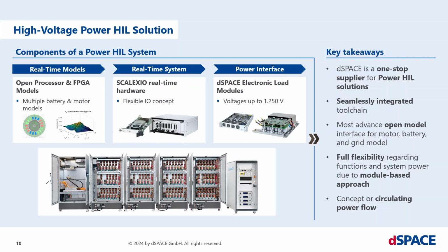With the Scalexio environment, I have the full flexibility to add exactly these components that I need to run these models in real time. If I need a second processor, just add a second processor board. If I need additional I/O functionalities, just add these functionalities. That's the flexibility of the Scalexio environment. With these two components, we are now able to run signal hardware in the loop tests because I have the real-time models and I have the possibility to bring it on a signal level.